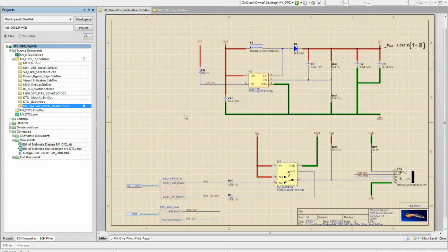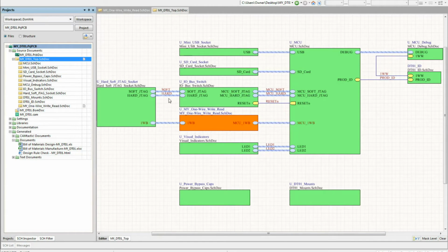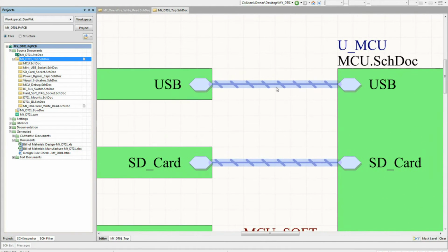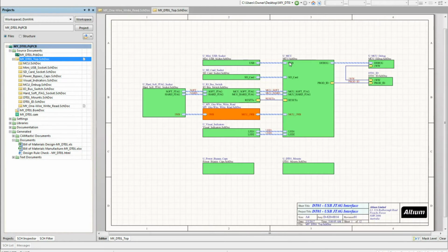And you'll build a lower level schematic, and then you'll build a top level schematic and create the hierarchical block for it. And after connecting all the components, you'll see how Altium Designer's powerful signal harness capabilities can help you produce a concise top-level schematic that instantly provides a coherent snapshot of your product's connectivity. Like in here, for example, you zoom in here and you can see that this signal harness is really showing that there are 4 signals going back and forth between these lower-level schematics.